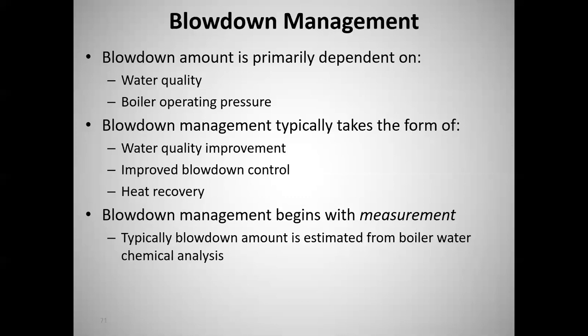Okay, blowdown management typically takes the form of improved water quality, improved blowdown control instead of manual, go to an automatic controller, and heat recovery. Okay. Blowdown management begins with measurement. Typical blowdown amount is estimated from boiler water chemical analysis.